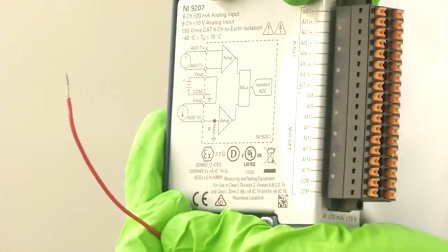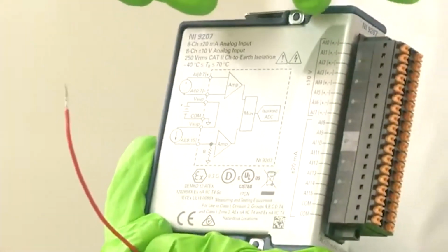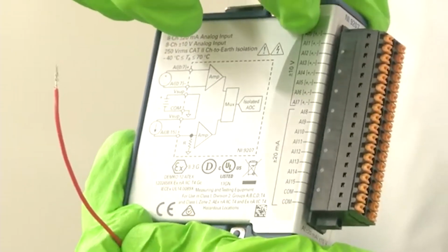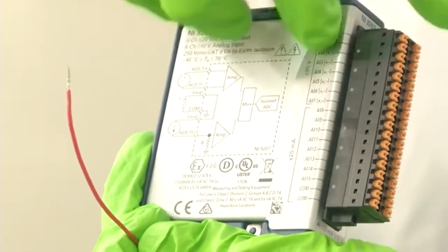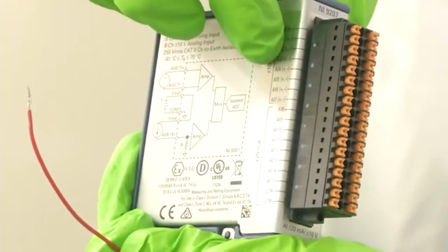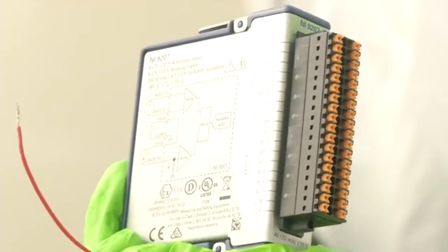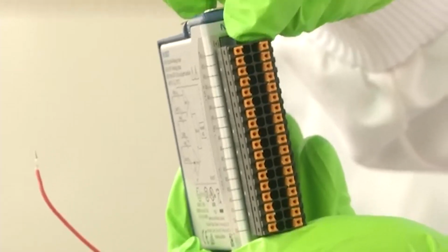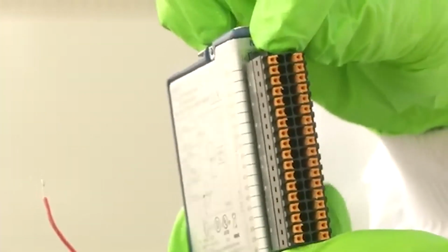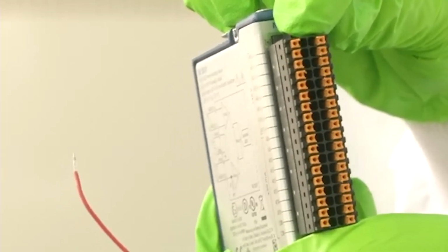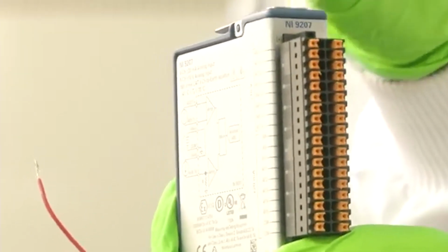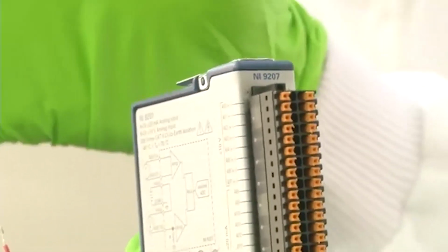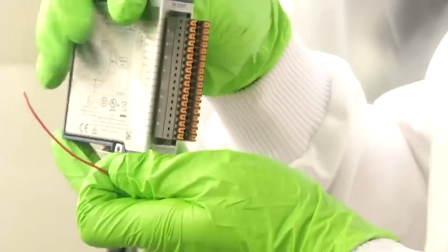So, here if you see there are different numbers of channels starting from 0 to 7. So, in total it has 8 channels for analog acquisition, which can measure up to plus or minus 10 volts. It has both a positive terminal and a negative terminal. What it does is that it can measure a differential input. In some cases, when you are using a quarter bridge, a half bridge, or a full bridge, whatever voltage signal is generated from the bridge is not an independent voltage, it is a differential output voltage. So, if I want to make use of a differential input, one way to do it is to make use of this device.